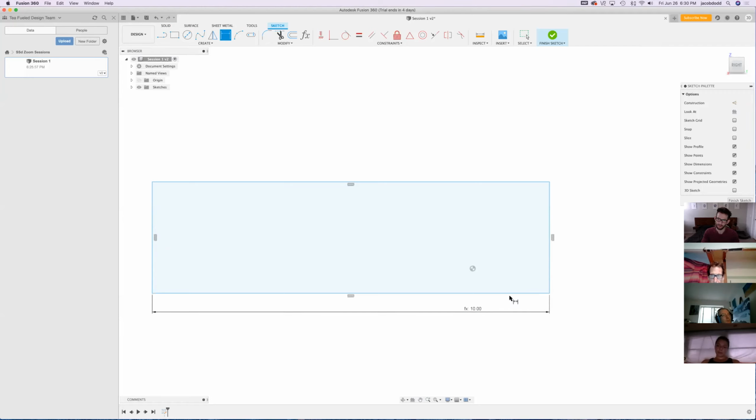So then we need to tell it that the height of this shelf from the side is going to be the thickness of the wood. So in this case, we can either click on the side here and drag out. I'm going to hit escape to get out of that, or we can click once here and then once at the top, and you see both those lines are highlighted now. And we can then click to set the dimension and say that it's the thickness and hit enter to lock that in.